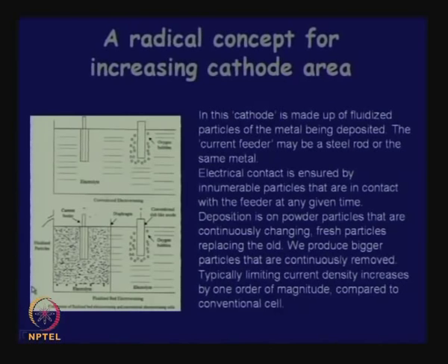and you must have a screen to take out a certain fraction of particles. So, you bring in more and more seeds. By adding a certain amount of smaller size particles, you get larger size particles. You can do something more also. In this, you can take a different kind of metal particles, fluidize them, and have them coated with the metal that is being deposited. You can do that also.